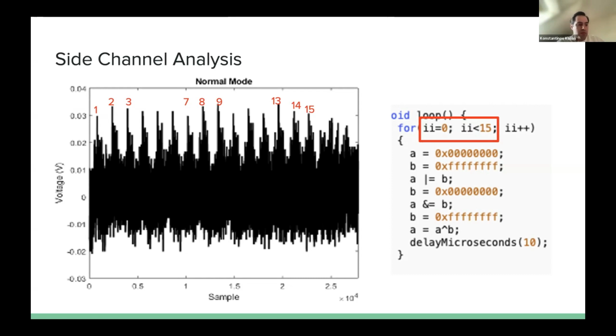In fact, the analysis of EM signals of a program has application to external and totally passive intrusion detection. Through side channel analysis, it is possible to answer questions such as, is your code infected with malware? Other well-known applications of side channel analysis include the detection of information leakage. In other words, we can answer questions such as, does your code leak information regarding, for example, important cryptographic operations that take place inside your device?